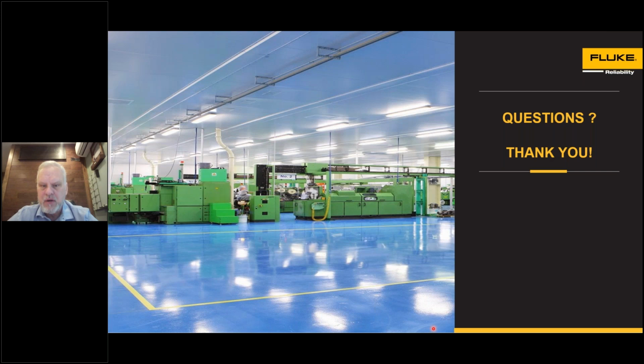And the other part of that answer is there are certain machines that do vary speed that are not a good application, and those I would call constantly changing speed. Things like downcoilers and unwinders in paper factories, where the machine speed is changing all the time. So when I say it's capable of variable speed machines, that supposes that the machine speed will be at least constant or relatively constant throughout the sample period of time, which is just a few seconds, once a day.